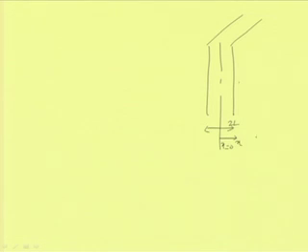Heat is being conducted in this side and this side from both the surfaces. According to our definitions, this is T infinity, and at the beginning the temperature was T i, the initial condition that we have seen in previous cases, and the temperature at this point is the center line temperature, which is nothing but T0.